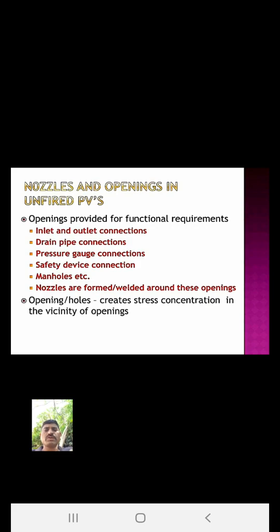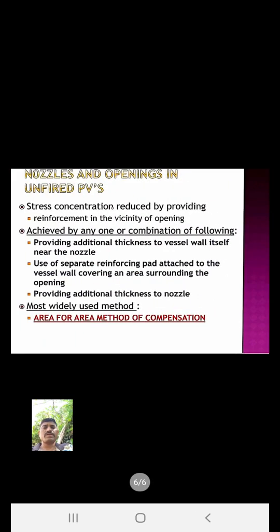Openings or holes create stress concentration in the vicinity of the openings. If you have removed some area, then you should add some area back at that place. Then how to add that? Because they create some stress concentration at the opening, outlet or drain pipe connections.